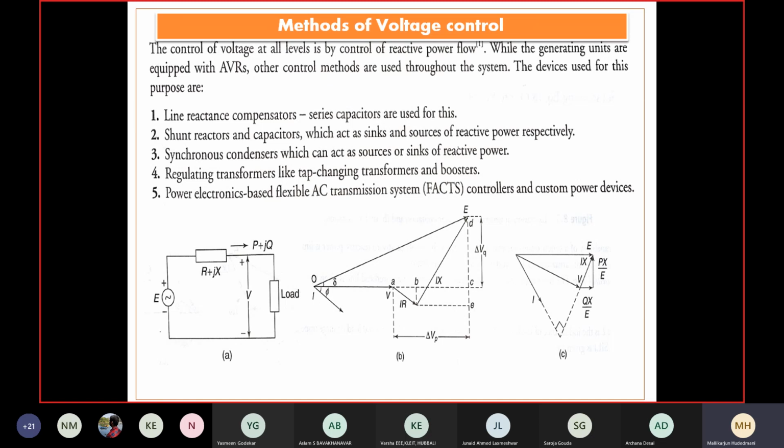Suddenly the load is removed. What will happen? The highly compensated line suffers immediately, because it was compensating the reactive part and making things work. Suddenly the load is removed, and the overcompensation is seen immediately on removal of the load.